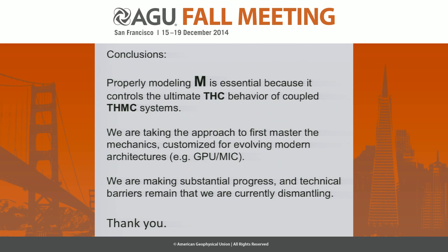Well, there are some technical problems that you come across, and that is the GPU. At least the first generation of them hated to invert any sort of matrix. They're very good at explicit finite difference because you just march forward in time very quickly. But they don't like to invert, so all implicit methods sort of go out the window.